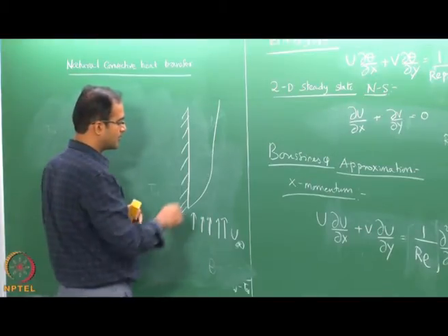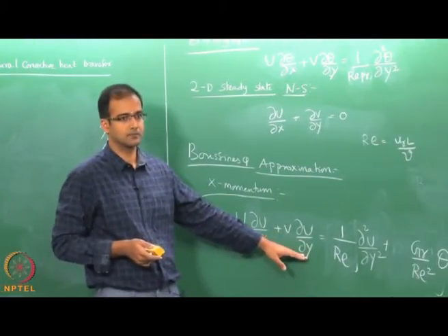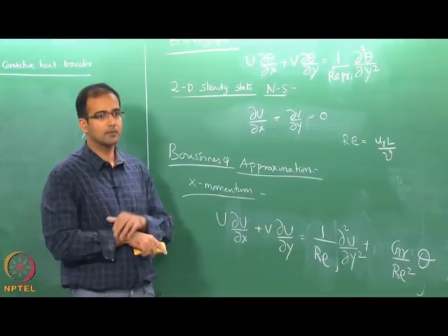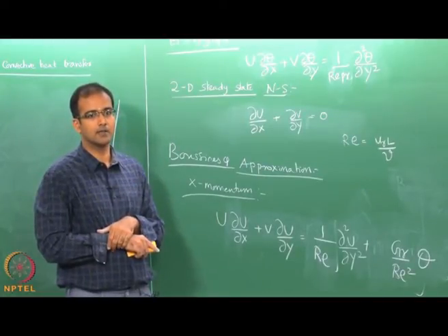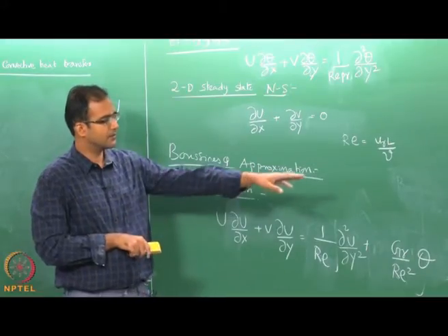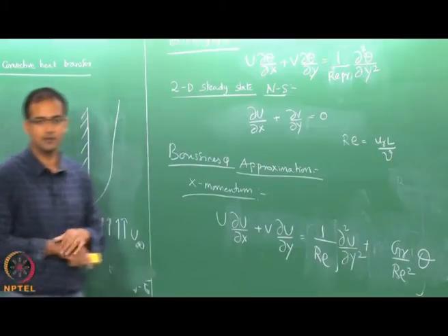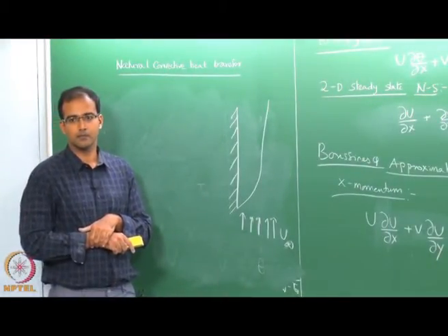Okay. So, in such a case the same equations are valid, right. But in that case your u reference you can actually use as u infinity, because even if you do not have any temperature difference, the forced convective boundary layer will still exist. Okay.